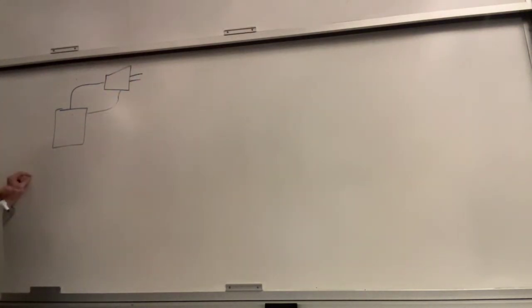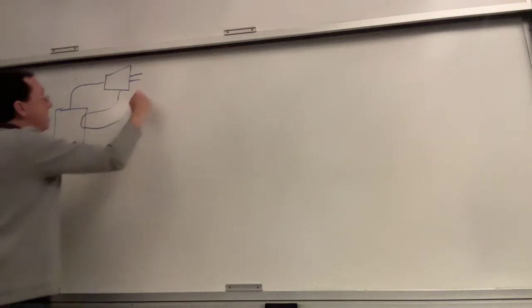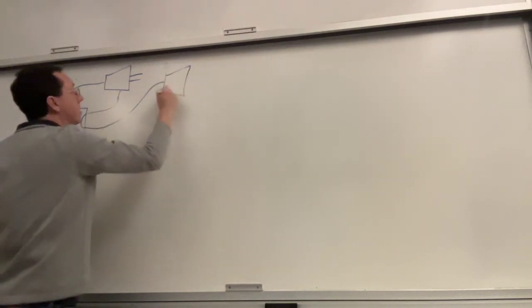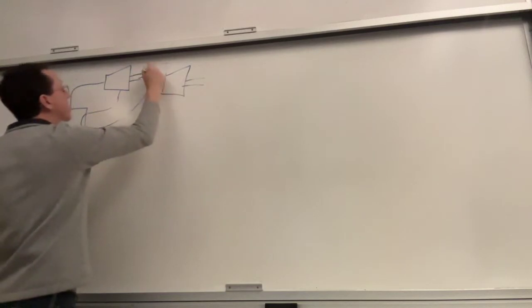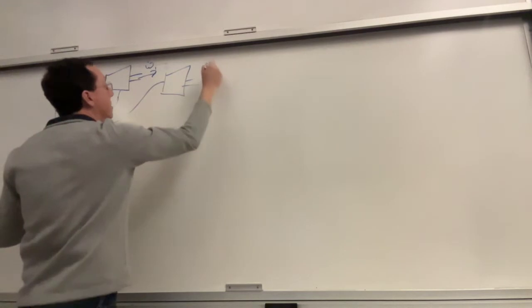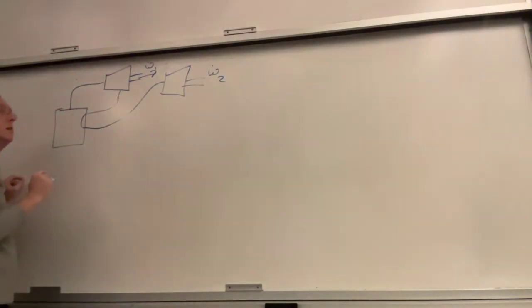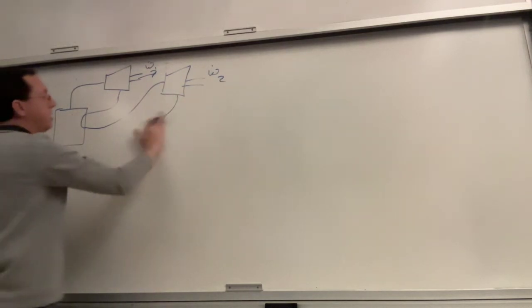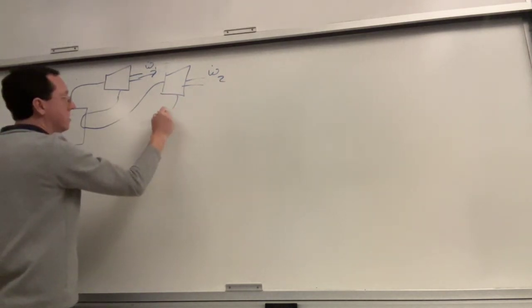Depending on the numbers, I think in the homework problem, you bring it a little bit into the mixed state, but whatever. You just reheat it back into steam again, and then run it into another turbine. You have work out, so you have W1 and you have W2 from the reheat turbine, and then you run it into your condenser.